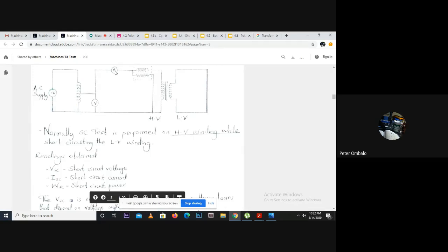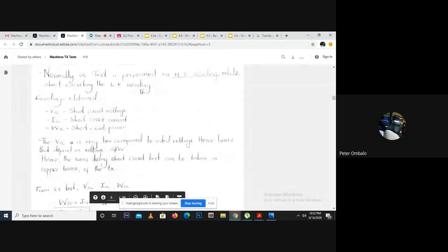And we know it's the current that flows through the resistance and the reactance. So the current is going to excite the resistance and the reactance, and so there's going to be copper losses. There's going to be very low iron losses or core losses, next to negligible. So then whatever the wattmeter is going to measure in a short circuit test is going to be assumed to be purely the core losses, the copper losses, I'm sorry.